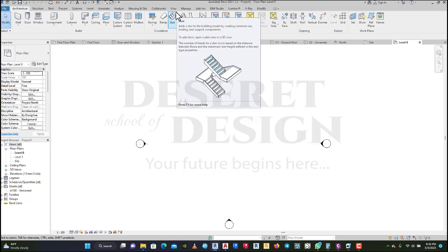I have an image. So you have a drawing, it's an image. The drawing comes with the design and everything, the floor plan I mean, but it doesn't give you length or width or those things. You have only areas of the spaces done. Now what you do is that first of all you need to upload the image into your project.